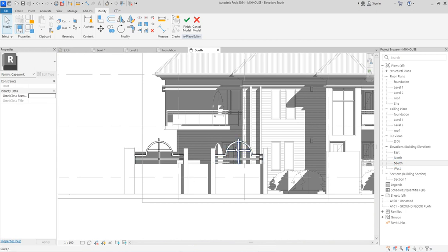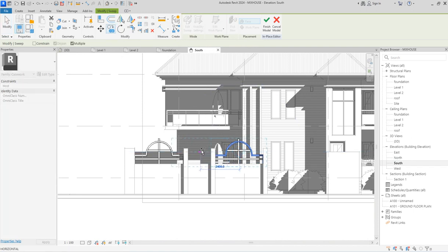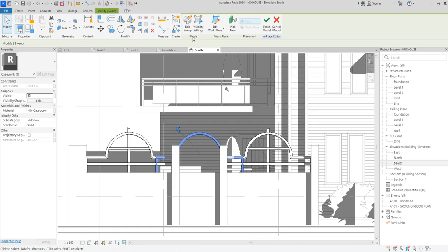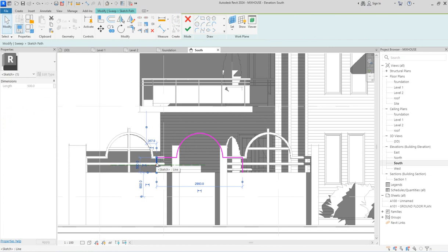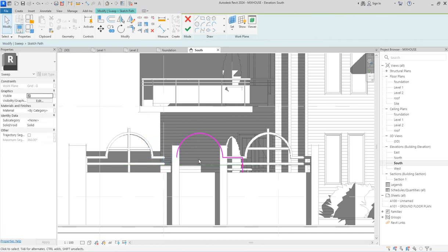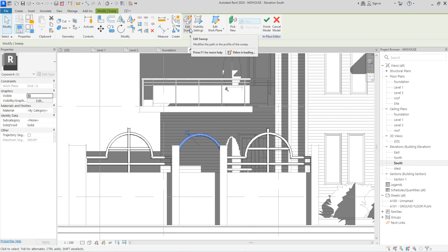We are still going to use the same thing. So we copy this one here, but I'm not going to follow the same pattern. What we do here is edit sketch, and then you click here, you click here, you click, and you delete here. So you click finish in this space, adjust this, come down.